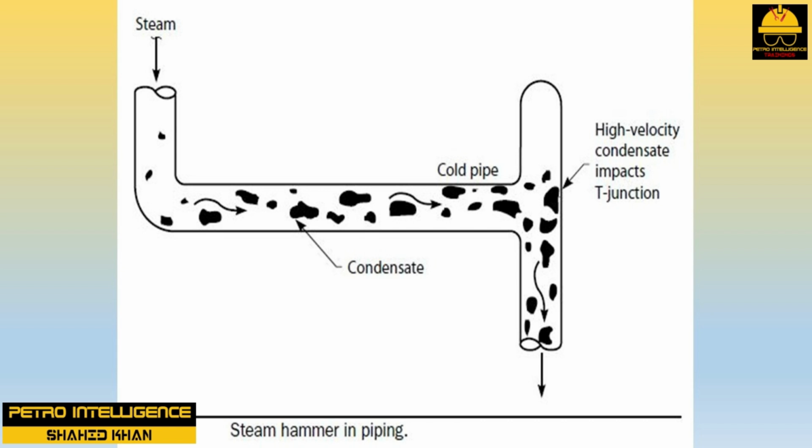Steam hammer is caused by the creation of localized cool areas in piping systems containing saturated steam. For example, when first introduced into idle pipes, the steam condenses rapidly upon encountering a length of cold piping. This creates slugs of water. The continuing rapid but localized condensation of steam further downstream creates areas of low pressure or even a partial vacuum.